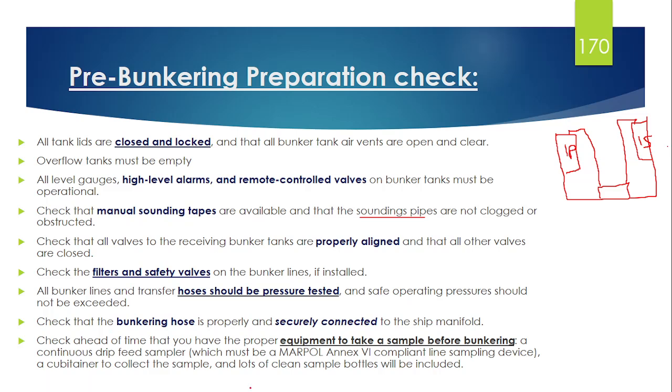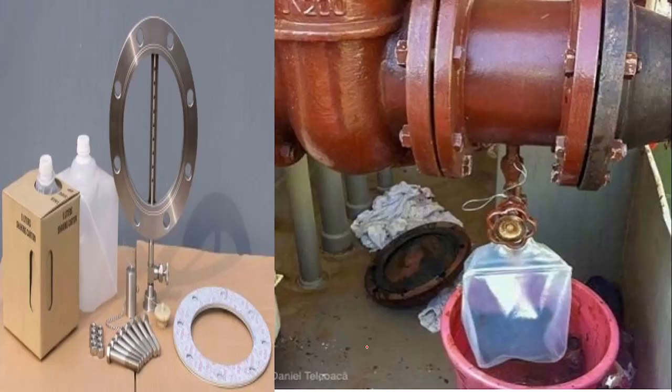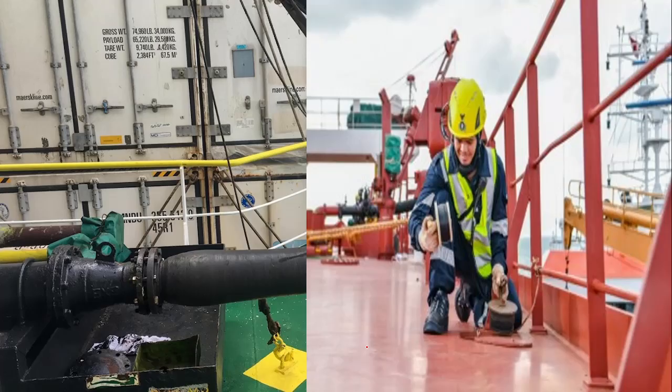After that, the most important thing is that you have to arrange SOPEP equipment near the bunkering point. What do I mean by that? Suppose you are taking bunker here. Okay, now this is the bunker point, so you should keep your SOPEP equipment here or here. SOPEP equipment is what we will talk about in a later slide.